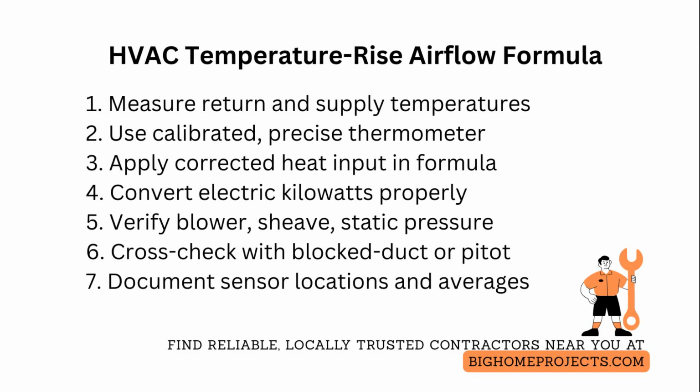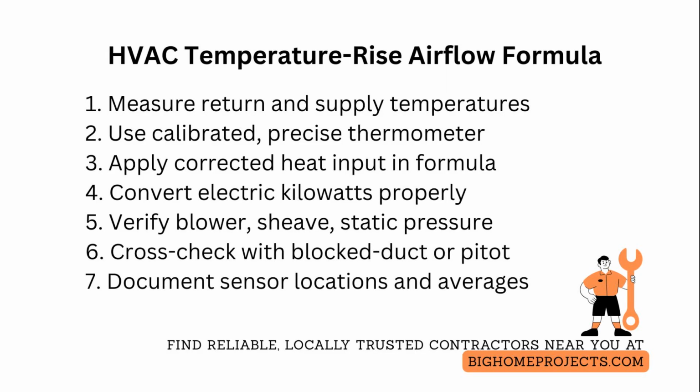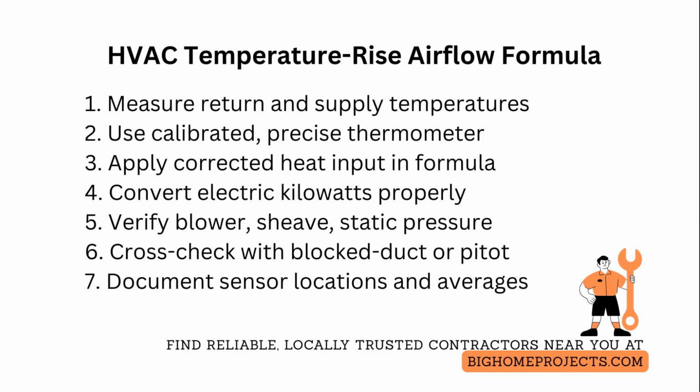Use a calibrated thermometer with at least 1/10 degree accuracy and log ambient temperature and wet bulb if humidity is high, because density corrections matter for precise cubic feet per minute calculations.